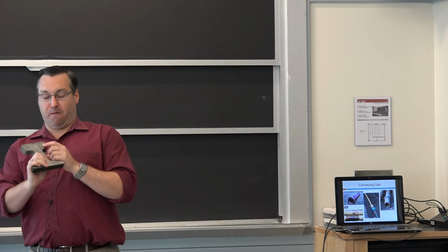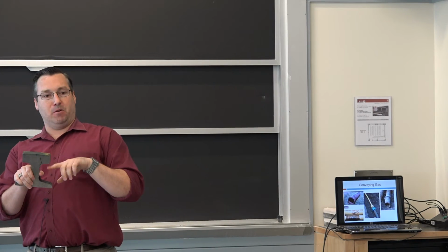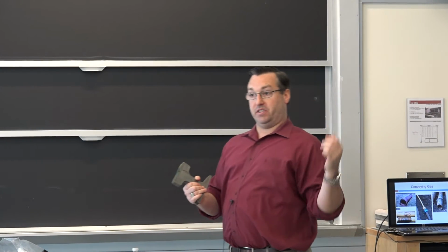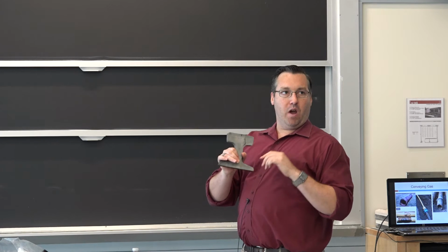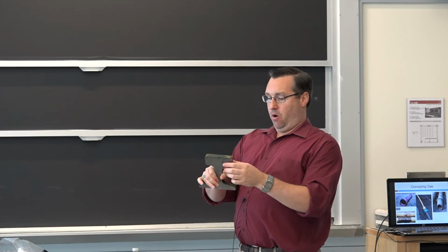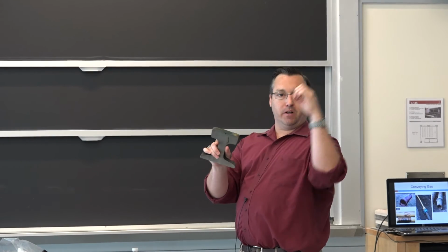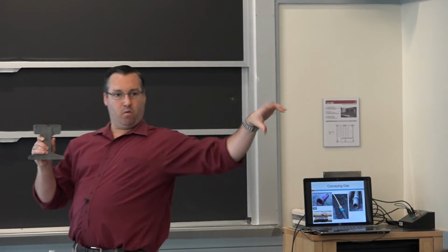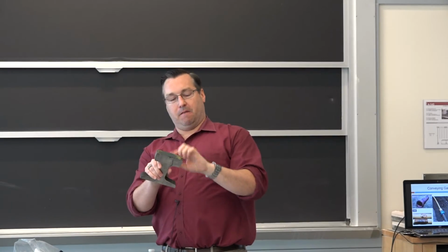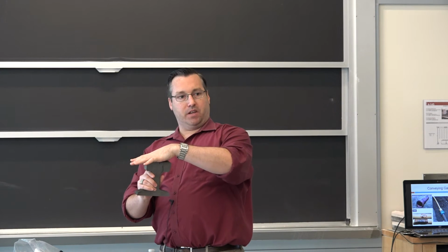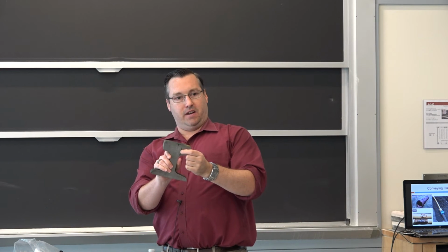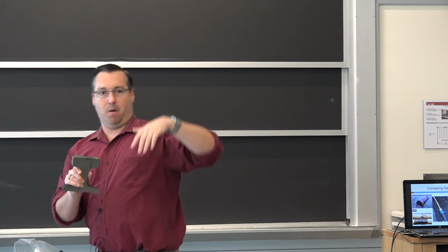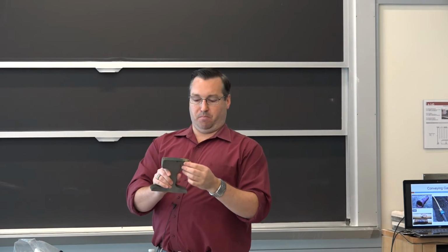All right, what this is called is a forging burst, and this happened during the manufacture of the rail. A lot of times you have hot, molten steel, and you need a refractory when you're manufacturing it, right? So chances are some of the refractory fell off, some of the brick casing that keeps the heat in the steel when the steel's molten. Chances are a piece of it fell off, and when the rail was getting extruded out, this area never melted because you had a refractory there whose melting temperature is above the process temperature.